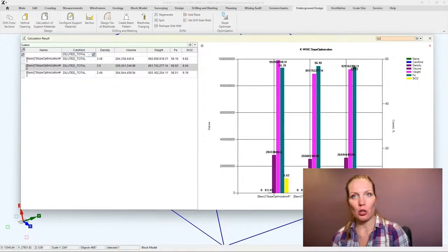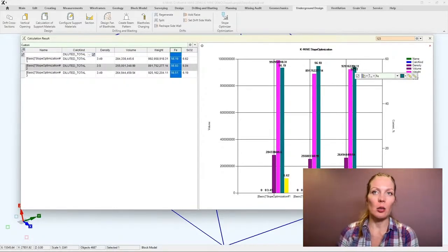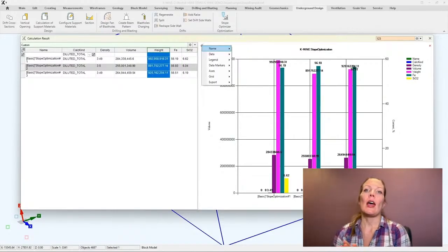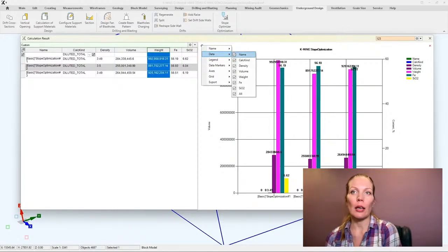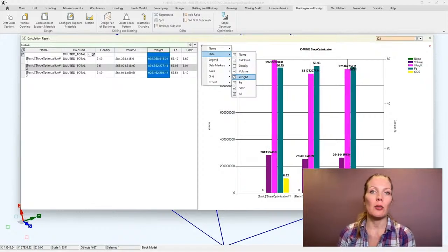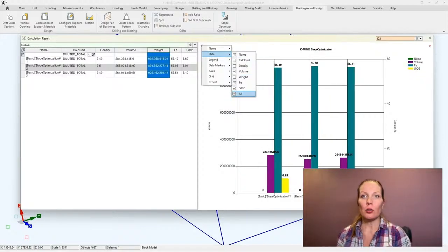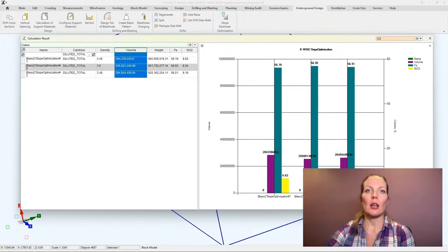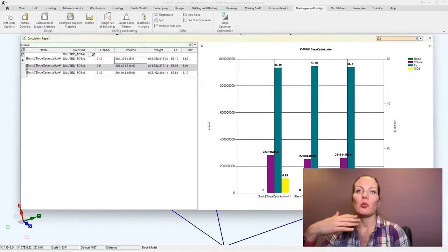Instead of trimming these stopes later in design, the team fed two additional constraints back into the optimizer: a limit on maximum access drift length and an assignment to a specific ventilation wing. With those constraints incorporated, more than 80% of the optimized stopes entered the project without any modification, and the time needed to align them with planning was cut almost in half.